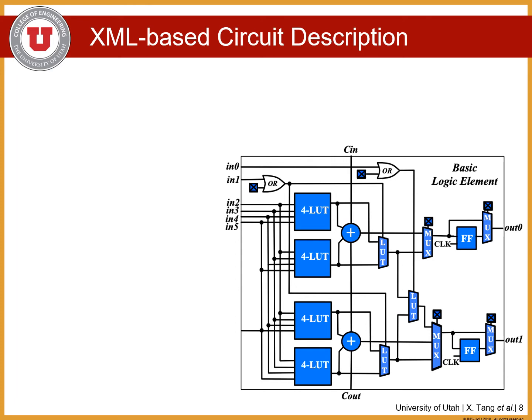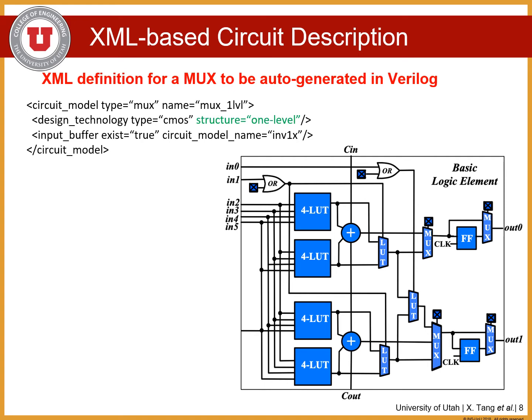So we offer an XML-based architecture description language to model the FPGA architecture as well as the circuit designs. For example, users can define a circuit model in XML, and OpenFPGA can auto-generate Verilog netlists.